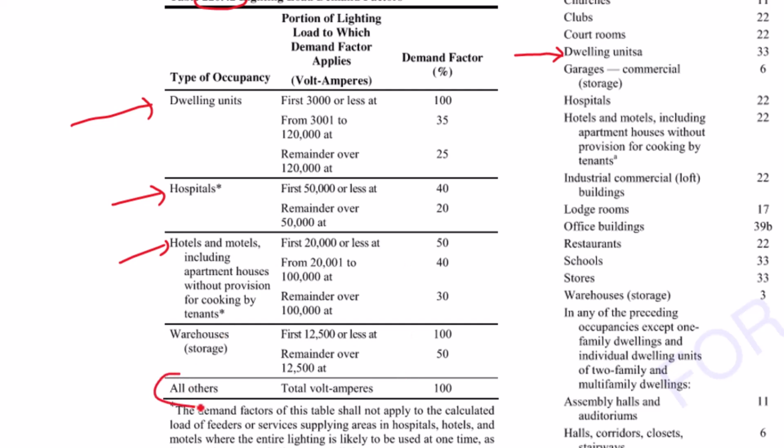And you can see here, for all others, such as commercial buildings, which we will cover later in this video, we have to take 100%. So basically, no demand factor in that case. We have to use the full load.